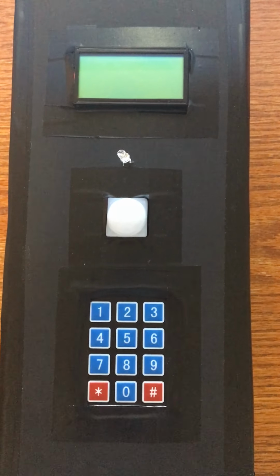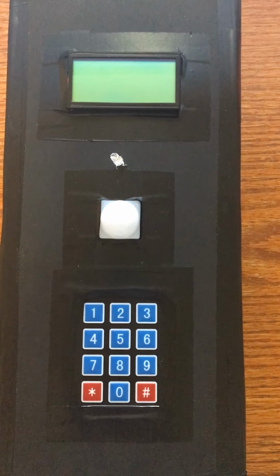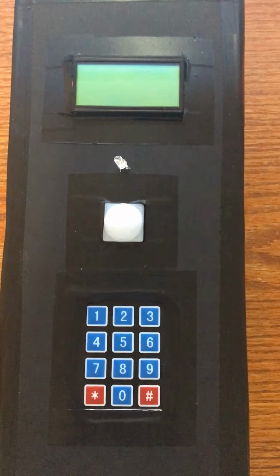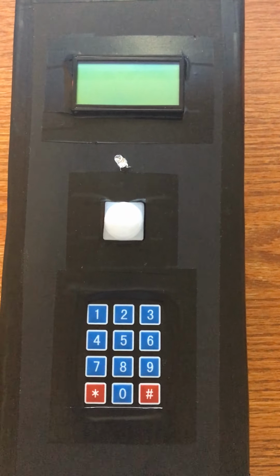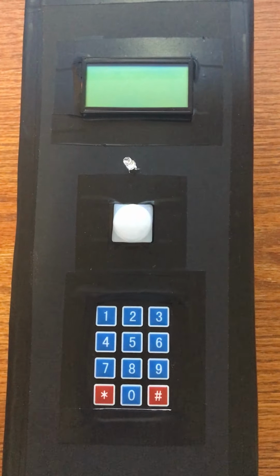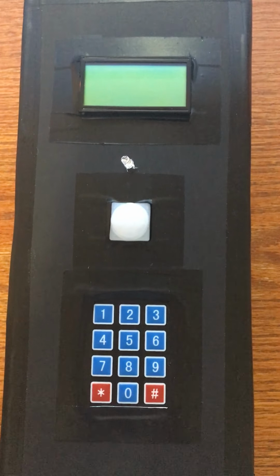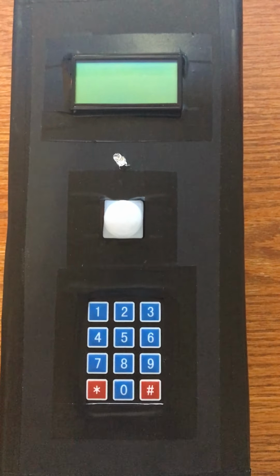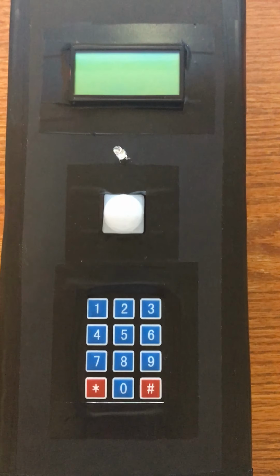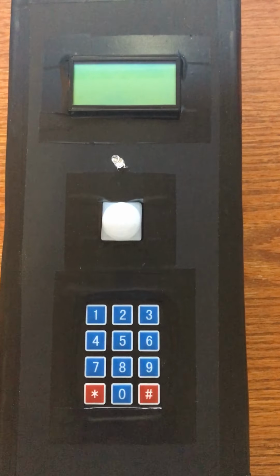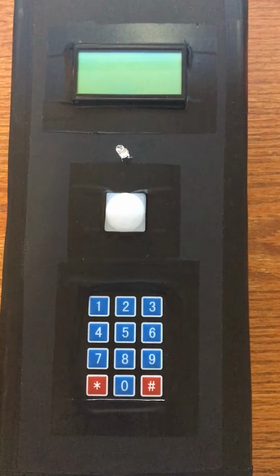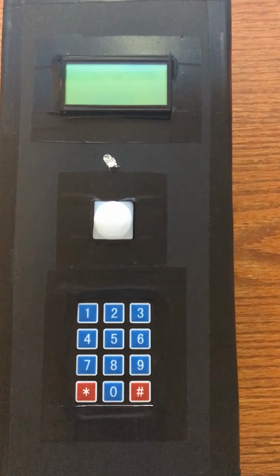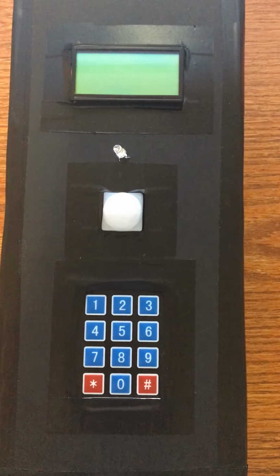If a key is pressed, the software architecture records its value, clears the display, sets the cursor at the beginning of the first line, and displays the key on the LCD. This is repeated 4 times until a 4-digit keypad input is recorded. If the keypad input does not match the default PIN, then the intruder detected stage is repeated. The software architecture then compares the keypad input with the default PIN. If the keypad input matches the default PIN, this triggers the alarm deactivated stage.